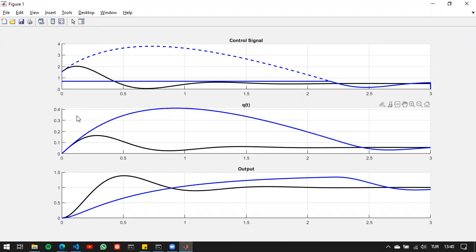So what happens is the following. The system actually wants to apply a certain control signal, but it is over the limit. Therefore, it becomes cut off. Therefore, we have a certain maximum value that we can apply, and that's it. Now, as this is the case, the controller gets more and more aggressive because it tried to apply a certain value to the system as an input, but it didn't get the result that it was expecting. Therefore, it increased the effect here, so it became more aggressive.